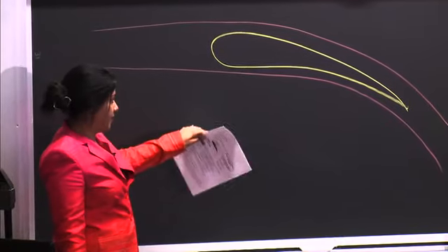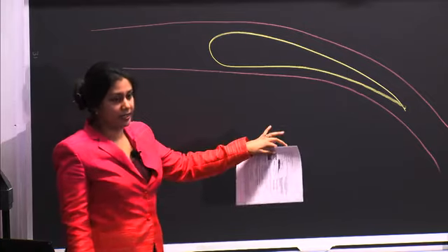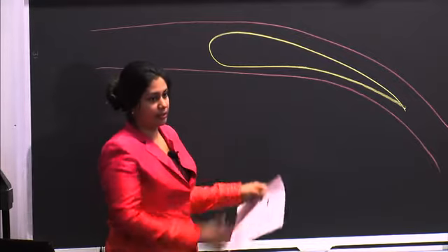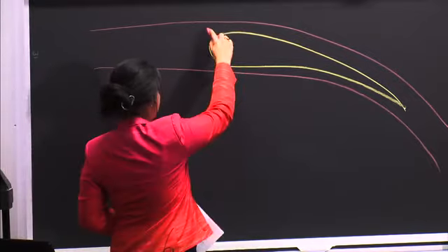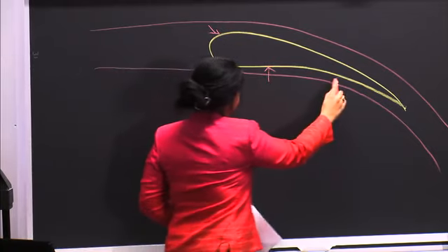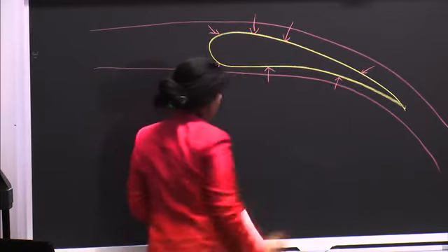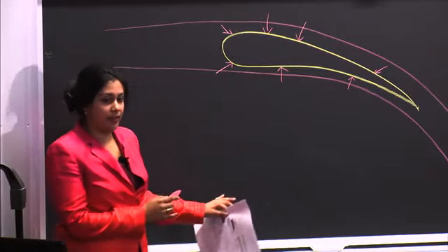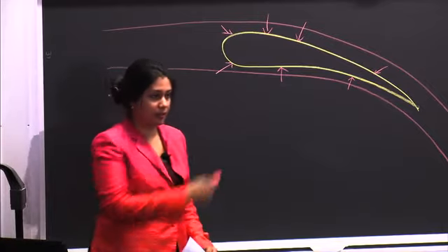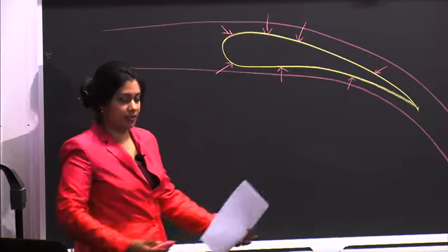Okay, so when you have this airfoil in a fluid, when the fluid is stationary, all of the fluid is exerting pressure on the airfoil. So you get all these little normal forces exerting pressure. When the fluid's not moving and the airfoil is stationary in the fluid, then all of those pressure forces, those normal forces or forces perpendicular, sum to zero, because there's no net force.